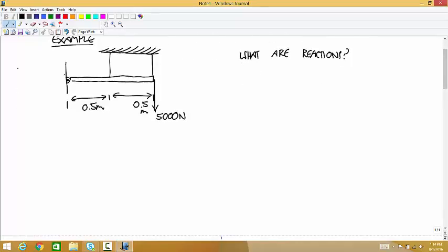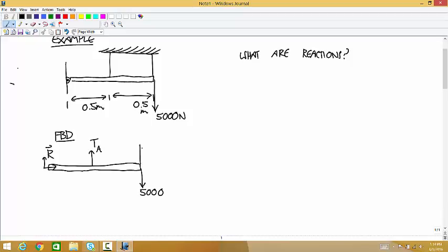Well, we're going to first do the statics problem, see what we have. We'll see that it's statically indeterminate. And then we'll use the geometry of how these things deform to figure out another equation to relate the variables we have. So free body diagram of the beam. We have a reaction at the wall. Call that R. We have the 5,000 Newton force at the end. And then we have an upward tension, I'll call this one TA, and an upward tension at the end, I'll call TB.